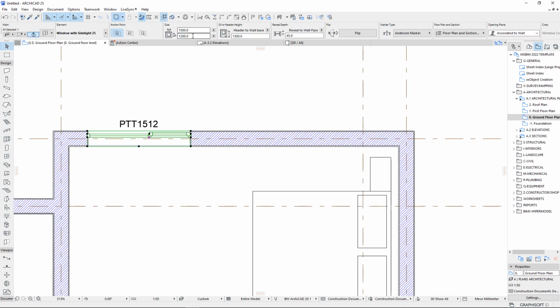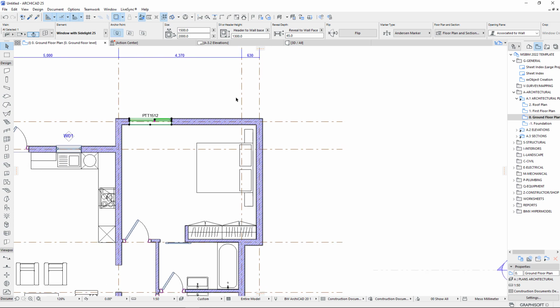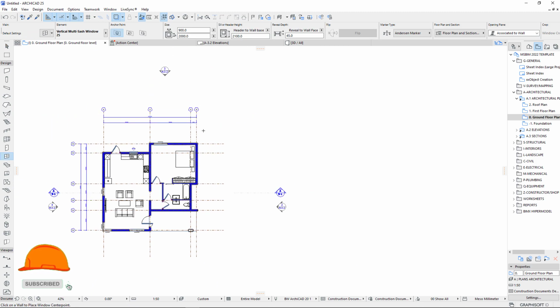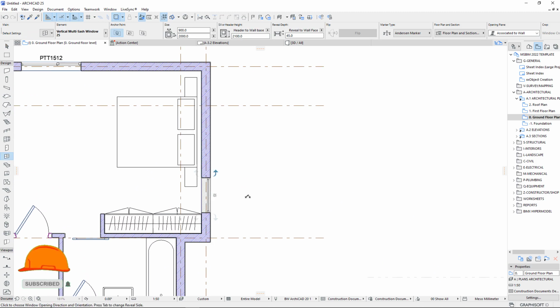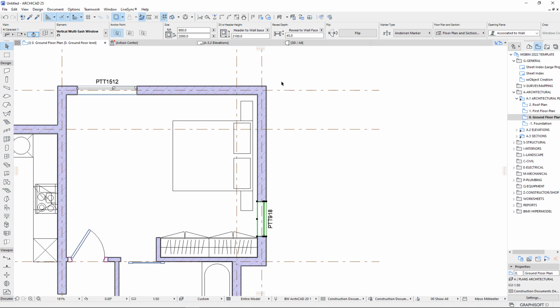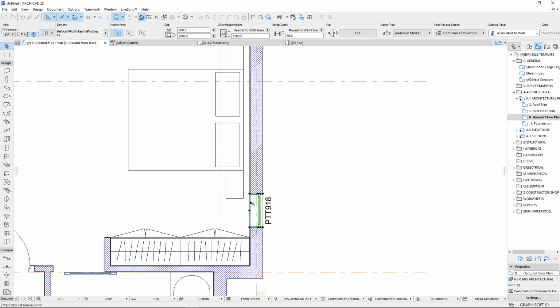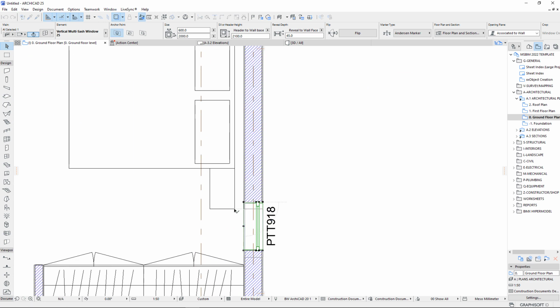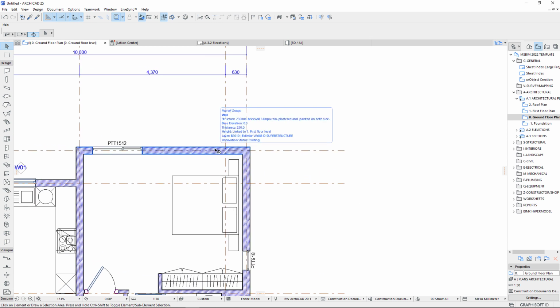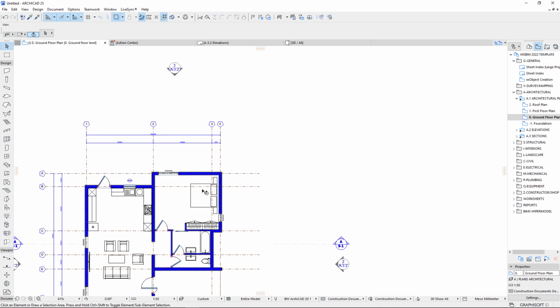This will be more like full height, which is 2 meters by 1.5. 1.5 is fine. And then I have a strip one similar to this one somewhere here. This is just to promote cross ventilation for this room, and I'll change the width to just 600. It's fine. Perfect. Like I said, just to promote cross ventilation. I can have another one here, but it's okay like this.